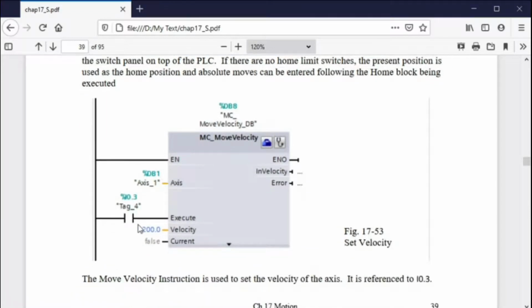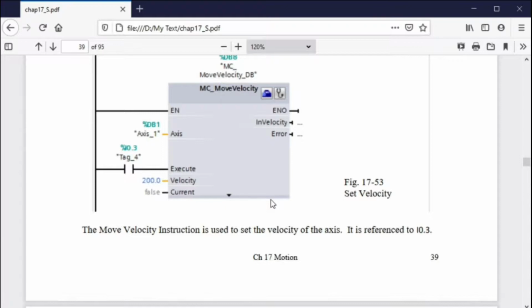And for the fourth switch, I0.3, if you give it a velocity here and flip that switch up, it will move. It should just move at a steady velocity. That's not moving to a position, but it's moving with a steady velocity. And that's how I would test to see if the drive is actually working. After you've done those first 3 switches, this is the fourth switch.